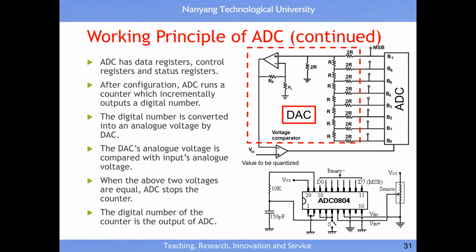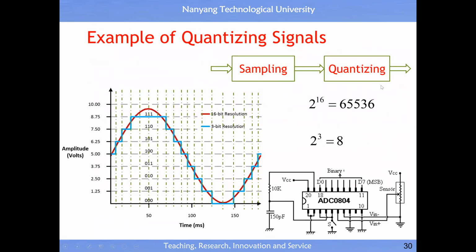Then what should be the design solution for the ADC? The ADC actually makes use of a DAC, because for a computer it's easier to predict all the possible numbers. I can always predict from 000, 001, 010. It's very fast. For each prediction, I do a comparison, because for each prediction I can do the DA conversion to get the analog value.